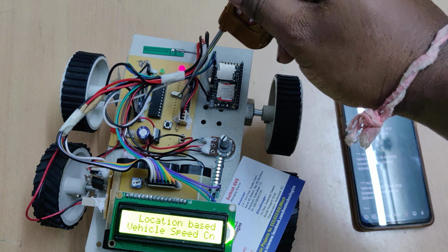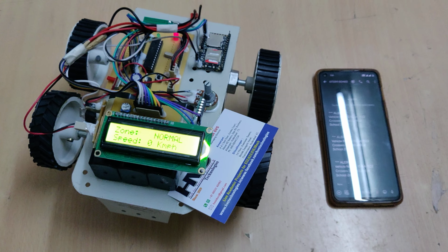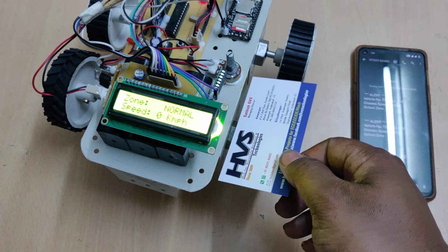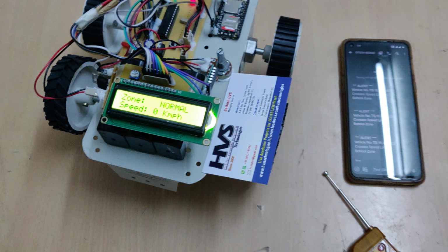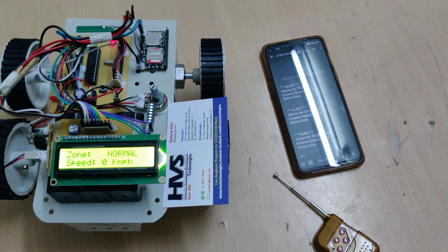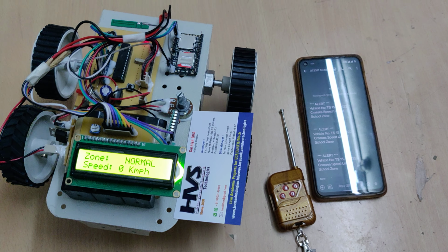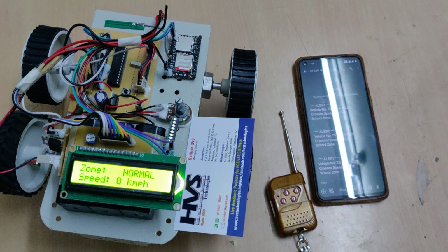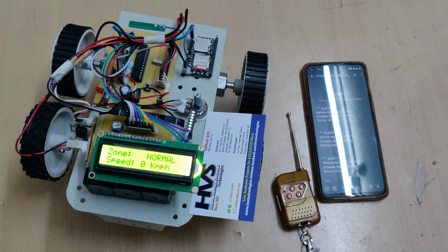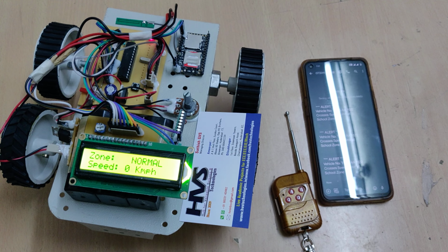Next, another important component is the crystal oscillator. This steel plated one is a crystal oscillator which will provide a 20 megahertz clock frequency to the microcontroller. The main purpose of the oscillating frequency is that we have provided the instructions in embedded C language. The controller needs one clock pulse per instruction, so we are providing 20 mega clock pulses, nothing but a 20 megahertz clock frequency. So the microcontroller can execute 20 mega instructions per second.